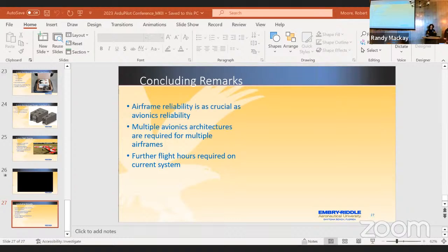So when we say the redundancy of avionics, do we mean the redundancy of sensors or the microcontroller? In this circumstance, we're talking about the microcontroller. Normally, for the last few years, we've obviously been talking sensors. Cube's been triple redundant on the sensors, but the single point of failure has always been the microcontroller. And that could be a mechanical failure, it could be an electrical failure, it could be a software failure. Lots of potential causes for something like that to happen.